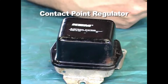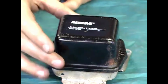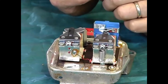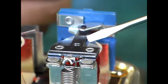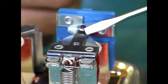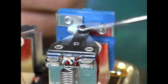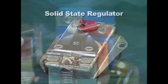Years ago, a contact point type regulator was used to control the alternator. A large set of contact points operated by magnetic coil action were used to open and close the circuit to the rotor as a means of controlling output. When voltage reached a preset value, the coil would act on the points to open or stop current flow to the rotor windings. Then, when voltage dropped, the points would snap closed to energize the rotor. This provided a crude means of voltage regulation.